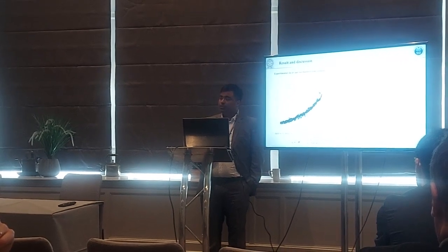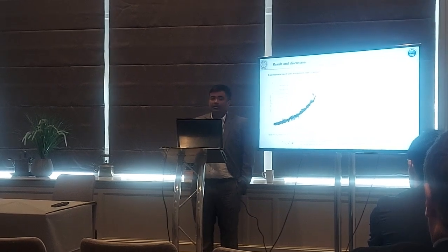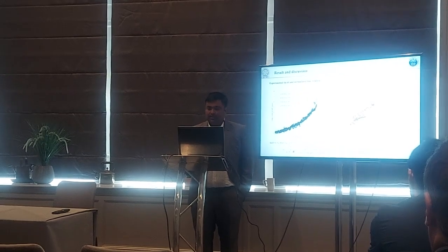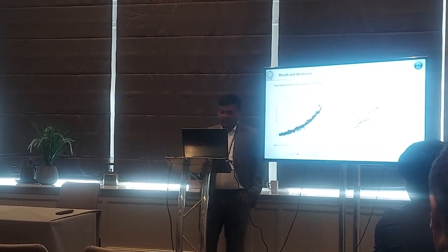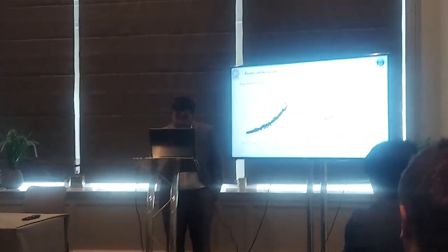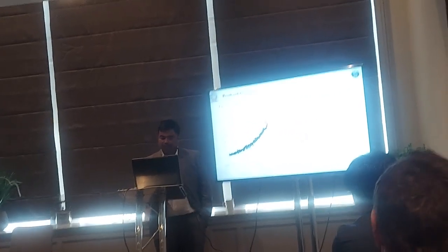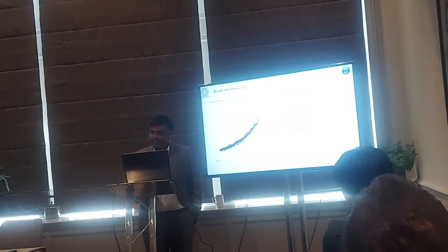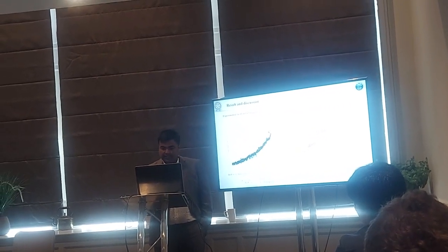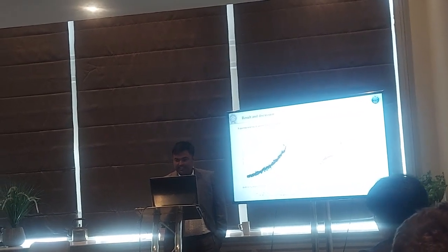And I changed something. I reduced the plastic effect and the elastic effect, because I want to see whether there are any plastic effects on creep or not. So for this I performed the analysis and analyzed the results. Then I found that the unfilled boxes show the normal C star versus dA by dt, for 10 kN, 12 kN, 14 kN and 16 kN.